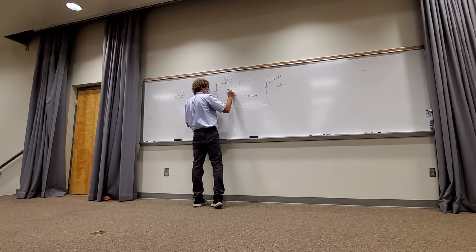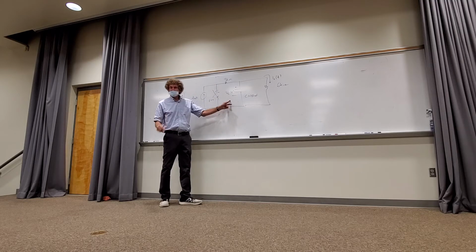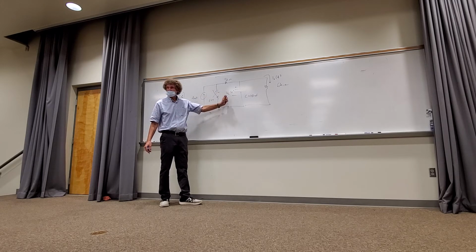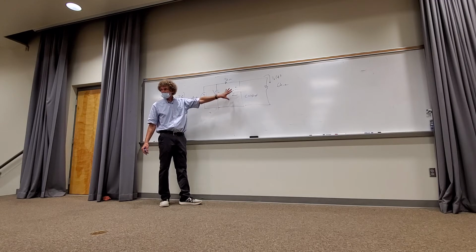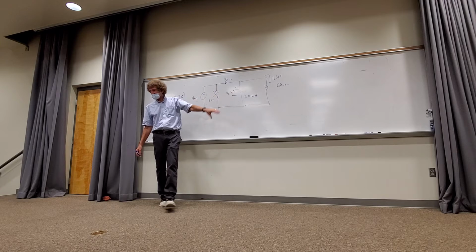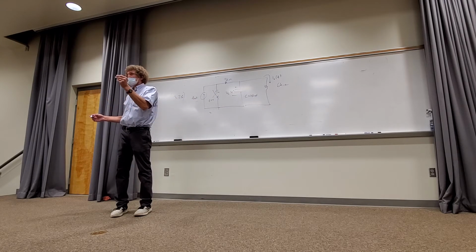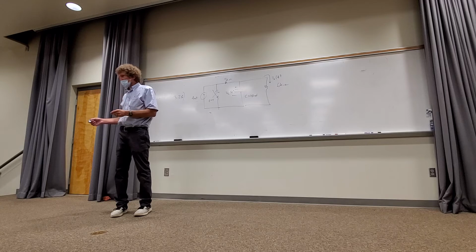Now just think about that. We get this voltage, if I want that current, do you all see that resistor's in parallel with this capacitor? Can you all see that? So if we have this voltage, to get that current, you just divide it by 6K. Remember, this is what you're after, not that, in a sense. This is the first thing you get. Remember, any RC problem, the thing you go for is the voltage as a function of time across the capacitor. Okay?